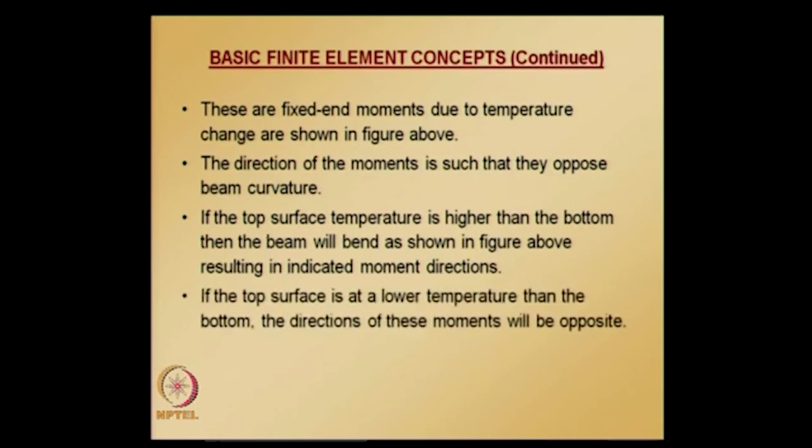And these points I just mentioned now. And please note that the direction of moments is always such as to oppose the beam curvature. Okay. And in both cases, whether the temperature of top surface is higher or lower, no shear stresses will be produced.